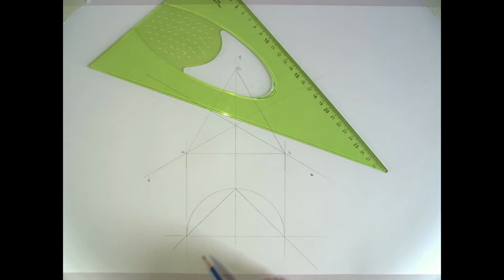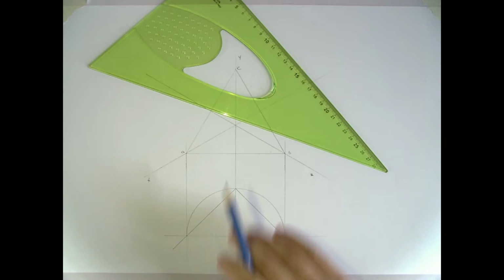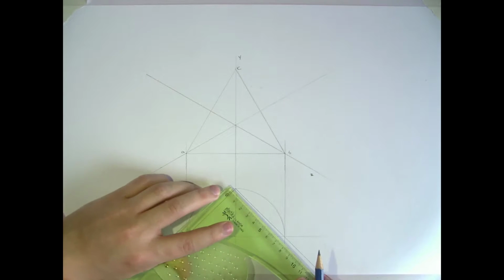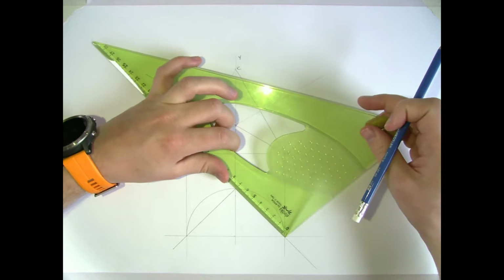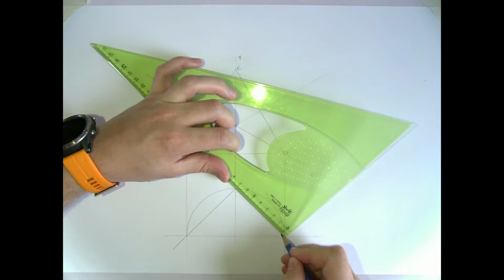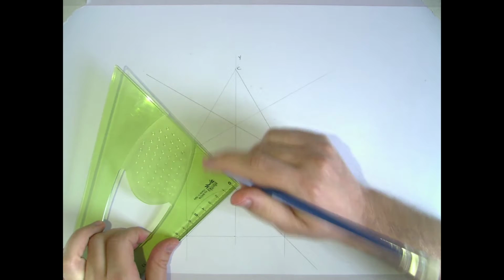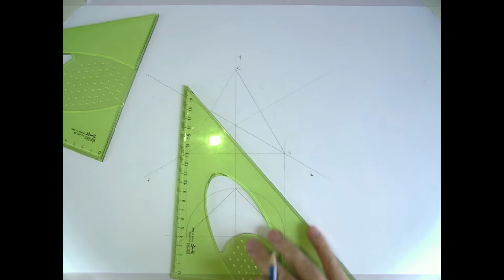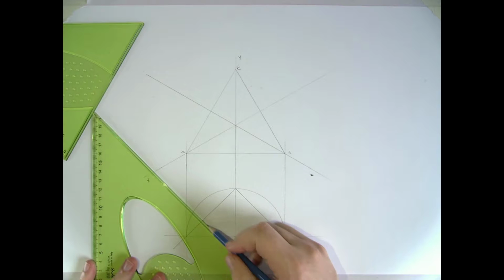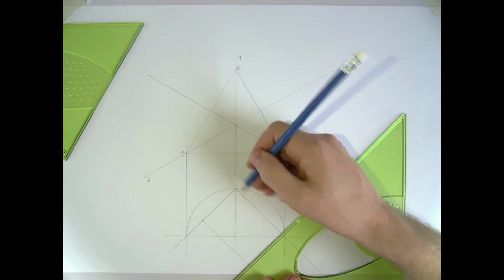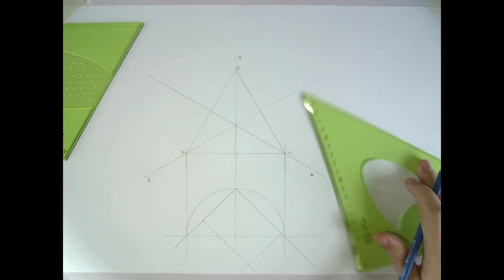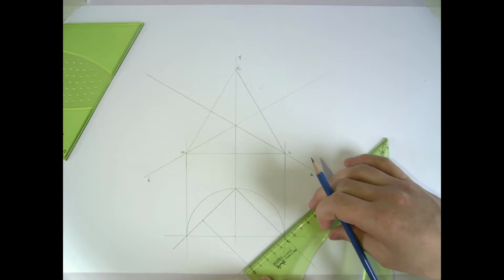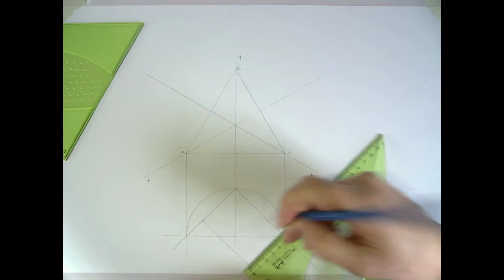So inside this now, we can draw our plan as given. It's 70 millimeters along this way, and 50 the opposite way, and as I said, it's 45 degrees, so you can use your 45-degree set square in plan to draw our lines. If you don't want to do that, you can still just use your sliding set squares, take them parallel to the sides here, and that will do it for you also. So we also have to find the ridge line, which is halfway along it. So that's 25.